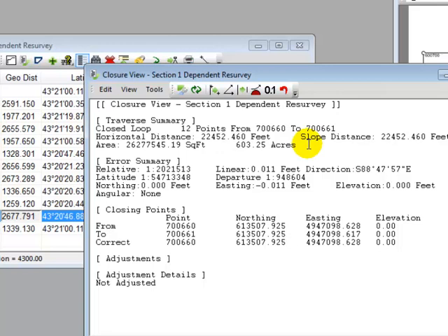And this is actually distance at the project elevation of 4,300 feet. Because remember, that's what the PLSS specifies, is that we're going to do geodetic or true bearings at a project elevation. And so the acreage, the distances that are displayed here, all of this is at the project elevation. Now, a lot of the computations are done on a state plane grid. That's how when we set up our coordinate reference system, that's why we got the convergences that we did. But Traverse PC understands the relationship there and gives us the proper information.